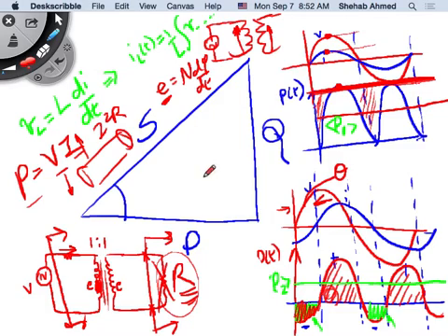So reactive power exists, and it adds more current. So I cannot rate my equipment simply by a 100 kilowatt load. That's a purely resistive load rated in kilowatts only, because there's no inductive component to it. It's only real power that's consumed in a resistor. But if I have to feed that load through a power system that has transformers and machines, I cannot ignore the extra current in the system.